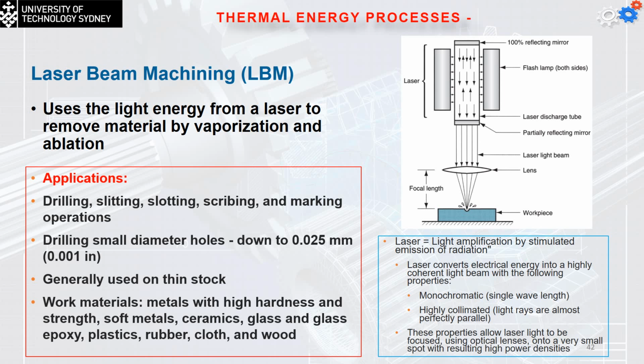So that's what's happening. If I take the laser to a reflective surface on a laser cutter, it's not going to cut it. So you have to avoid that. So it cannot cut aluminium, for example, because it's reflective. It's going to dissipate most of the light energy and diffuse the cutting operation.